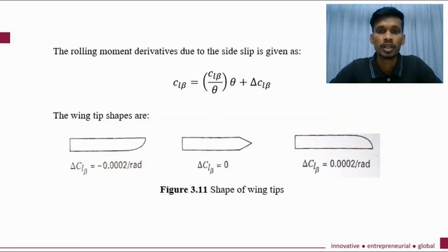This helps to stabilize the lateral or rolling effect when one wing gets lower than the other wing on the opposite side of the airplane. The static lateral stability of an aircraft involves consideration of rolling moments due to side slip. If an aircraft has favorable rolling moment due to side slip, a lateral displacement from wing level flight produces a side slip, and a side slip creates a rolling moment tending to return the aircraft to wing level flight. By this action, static lateral stability will be evident.